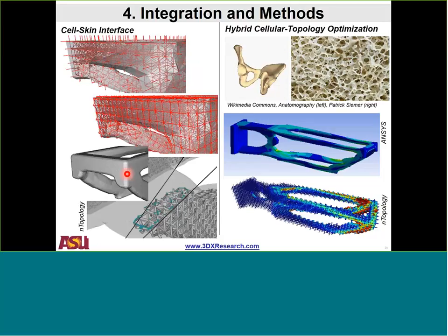There are other strategies for thermal and fluid-based strategy, but from a structural lightweighting standpoint, this is one way to think of it. And an example here is to start off with a geometry, perform a topology optimization on it, like I'm showing over here, and then use some cellular software to create your cellular structure in it. So it doesn't answer the question about what to do with the skin, and that's where ideas like gradation come in handy, where you eventually blend into the thickness.